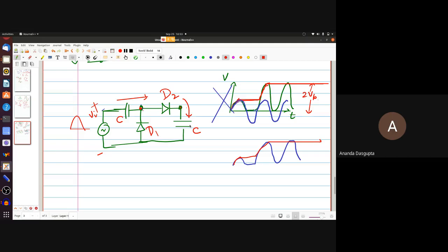And since we are assuming equal capacitances, that's important here, same potential drop across both of them, which means Vi has to get divided into Vi by 2 across both of them. So when this is an input signal, at least the output should look initially like this. Half as big for both this point and this point.